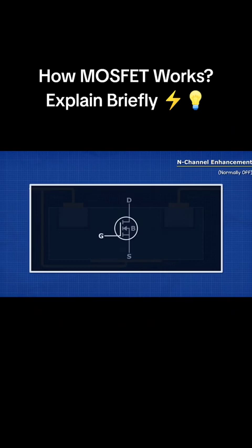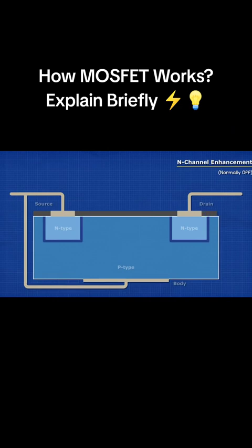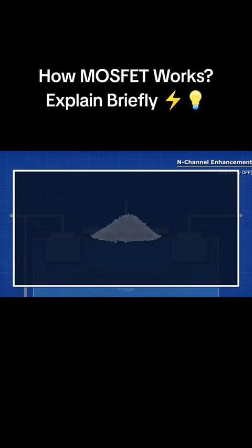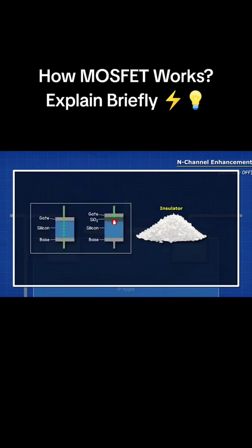That is why the symbol shows a drain terminal, a source terminal, and a base terminal, with the base connected directly to the source. We then have a layer of silicon dioxide over the semiconductors. A metal contact pad is placed on top of this, which forms the gate terminal. The silicon dioxide is an insulator with an extremely large resistance. This keeps the gate pins separated from the semiconductor and prevents current from being able to flow through this.